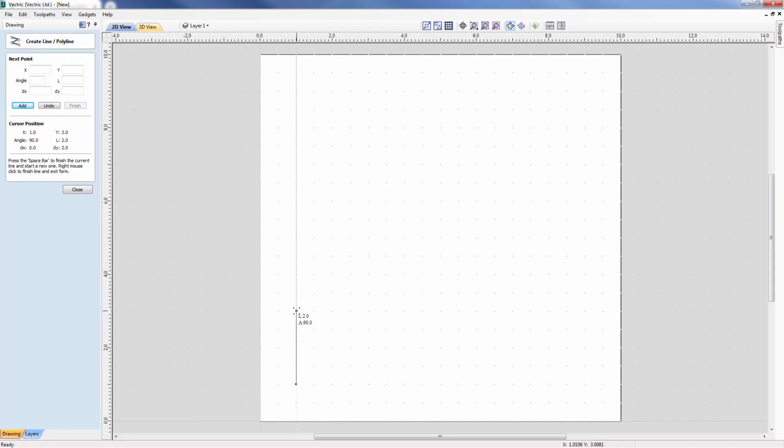So with this, I'm going to go upwards in Y by 3. So I'm just moving my cursor along the line that I want the distance to continue, and I hit 3 on the keyboard, and you'll notice in the lower right hand corner, roughly where my cursor is, you'll see the value that I'm about to enter appear at the bottom of the screen. So I'm just going to move in the direction. I hit 3 on the keyboard. You can see the value 3 now in the bottom right hand corner. I just hit return, and that will have incrementally created a new point, distance 3 in Y from the previous point.